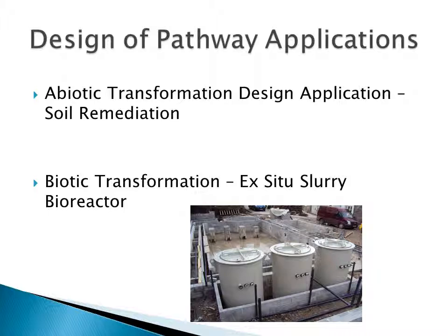An effective approach to the treatment of surface soils contaminated with chemicals susceptible to biodegradation is excavation followed by biological treatment in slurry reactors. The process provides an inexpensive means of treating soils contaminated with compounds that are rapidly metabolized by microbial communities. Slurry treatments are conducted in existing lagoons or in bioreactors designed and constructed for a specific solid hazardous waste that requires treatment.